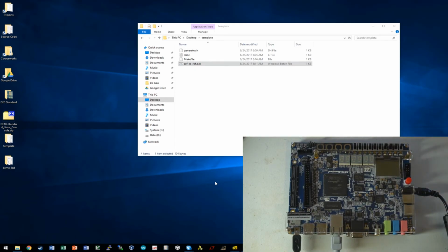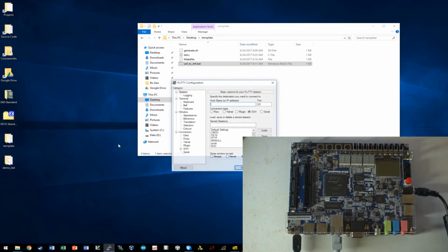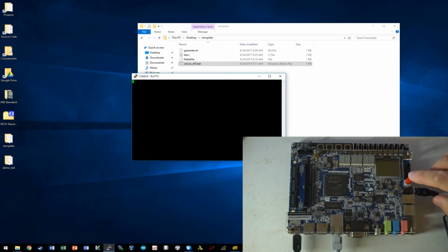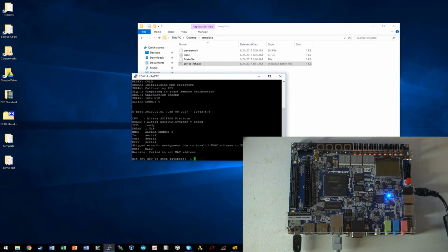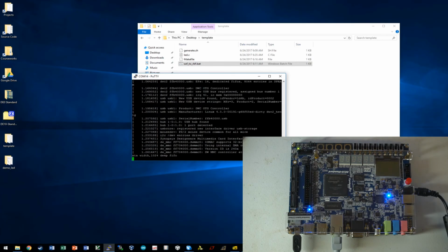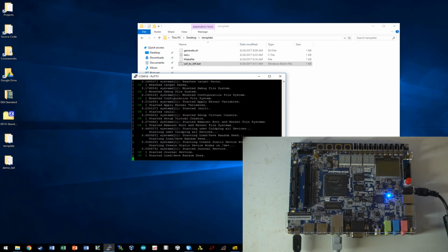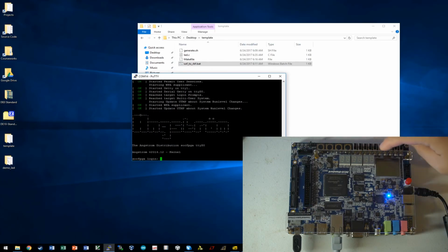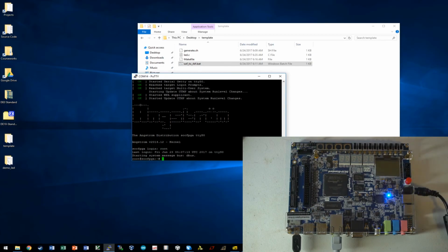Alright, let's boot up the system. Oh, before I do that, let's open the console. Okay, it used to be a 5-second delay, and I modified that to 1 second. And you can see the FPGA has been reconfigured, so all the LEDs don't have the pull-up anymore, so they are completely dark. That's normal. That means our configuration bit stream has been loaded to the FPGA.